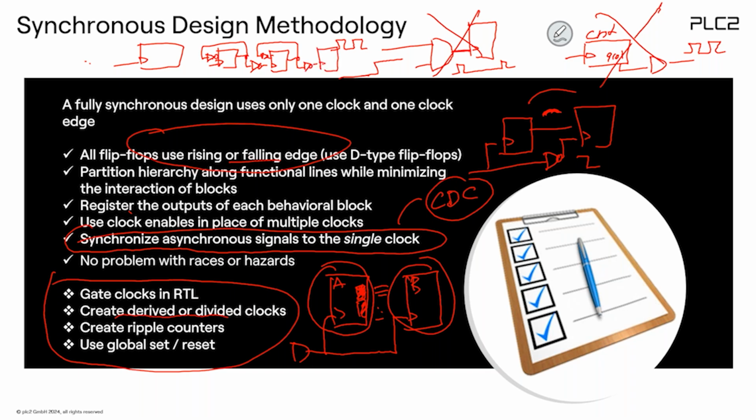And you see that's the problem, because we do have a clock 1 here, we do have a clock 2 here, we have clock 3 here. So this is a completely asynchronous design, because you never know the value. When is the value of the counter stable? So this is not really allowed. Please don't do this. And we will talk about the set and reset. There are some special things we need to know. So that's actually the methodology.